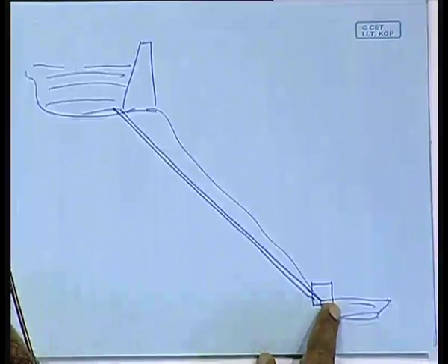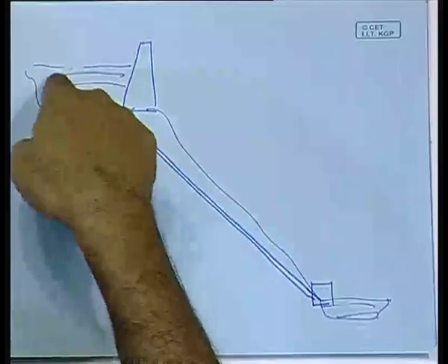If you keep it at a certain level, what is happening? The load curve is varying, load is going up and down. So when in the middle of the night the load goes down, what do you do with the power? You can do nothing with it. Okay. So you are normally forced to reduce the power generation in the power plant. That is why in many states where there is power shortage, you still hear cries that we have got power supplies at 2 o'clock in the morning. Right? You hear that. Now one of the nice things that one can do if there is a reservoir here is that during the night time when there is surplus power, use that to pump water up there.